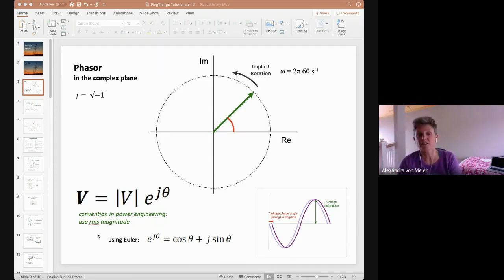One is the difference between voltage and current that's related to the power factor. The other is the difference between voltage in one place and voltage in another place. And that's related to long distance power transfer. Over short distances, you would barely be able to measure, that's why we have micro PMUs, a timing difference of just a degree or so. Over long distances, that becomes important.